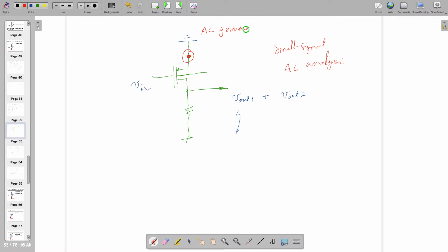Although VDD is connected, look at this. There is VDD connected, which has some ripple, but right now it's AC grounded. When you are considering just Vin and checking the Vout, and in the next phase of analysis, you are connecting here some voltage source named small v with subscript dd, and this one is ground. So then what kind of amplifier is it?